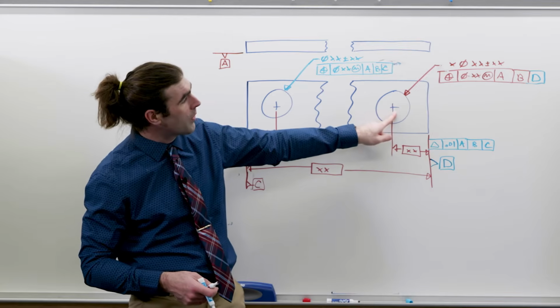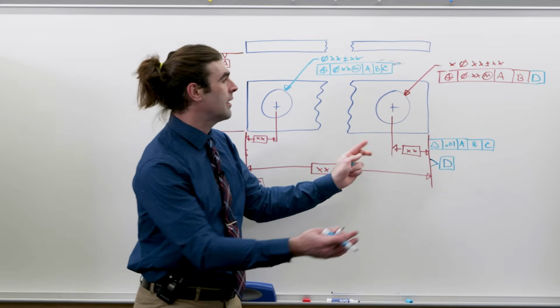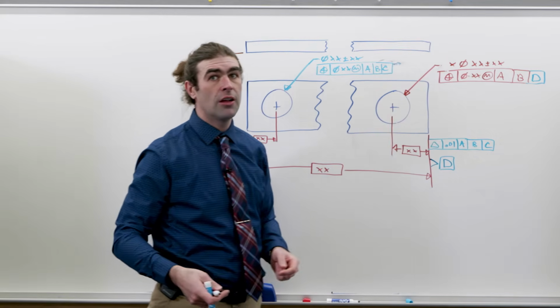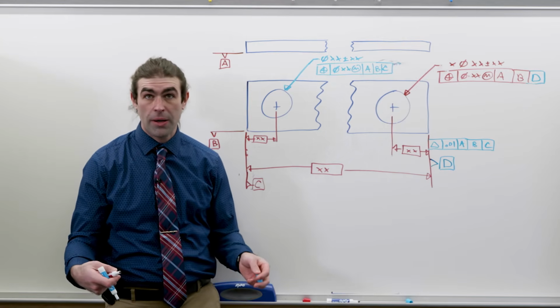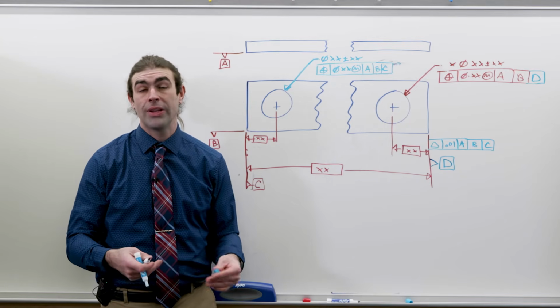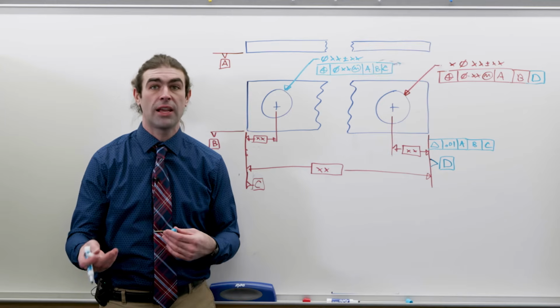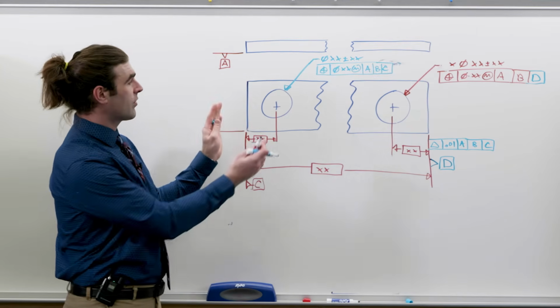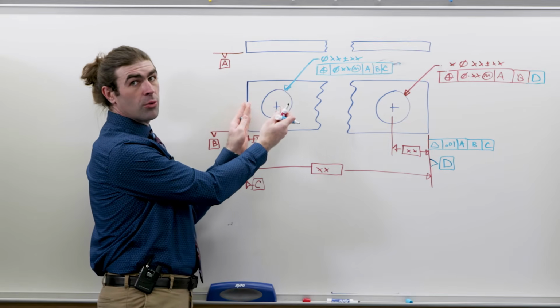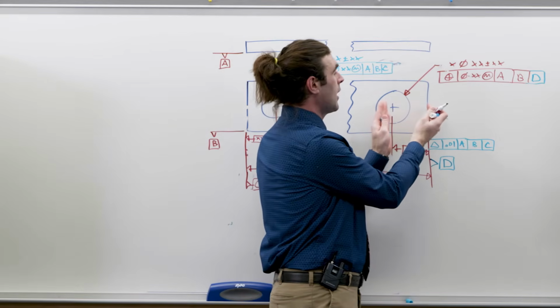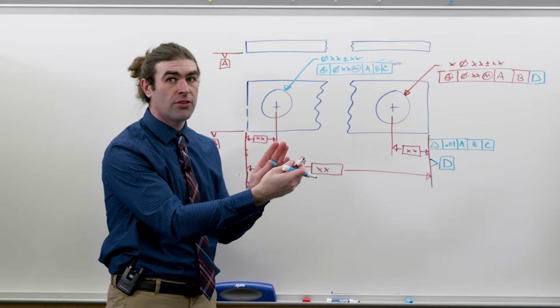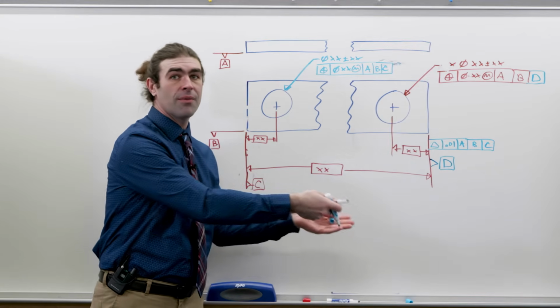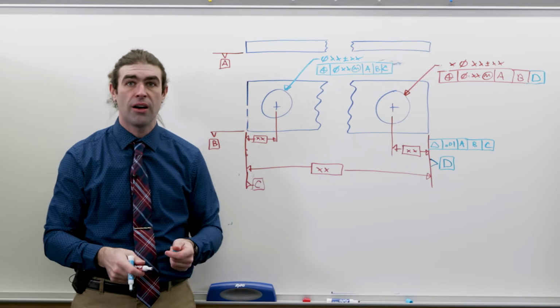Now this hole can be measured from A, B, D, from this side. So inspection-wise, it can be a little bit easier depending how you set it up. Functionally, this could help as well. If this hole is just sliding over something that has to do with one edge, it would be the same over here. You're measuring from the edge of the important side, not the total other side of the part.